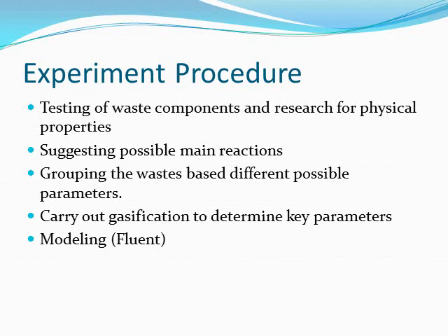Firstly is the testing of waste components and the research for some necessary physical properties of the waste. Some key properties of the waste, in my opinion, are elemental compositions, lower heating values, ash contents and compositions, moisture contents, volatile metal contents, and other contaminants in the waste. Then, based on the main components of the waste, suggest some possible main reactions that could happen in the gasifier.